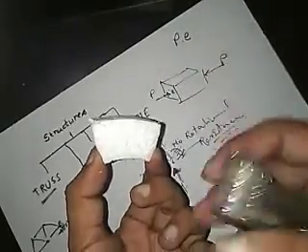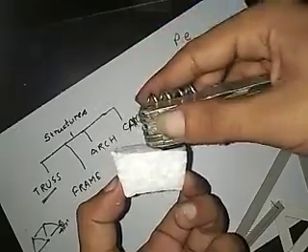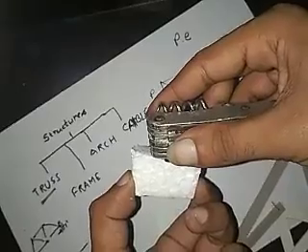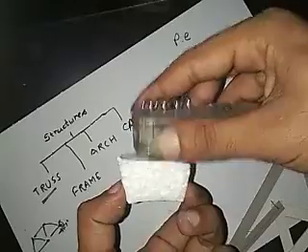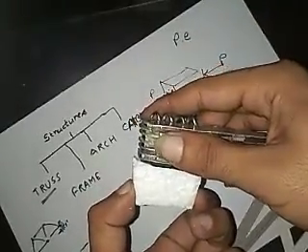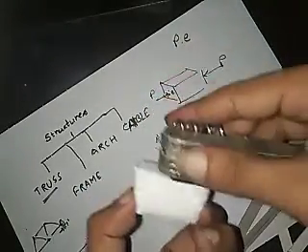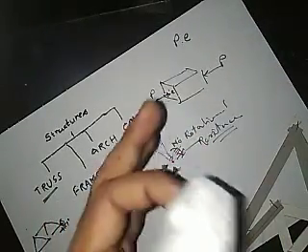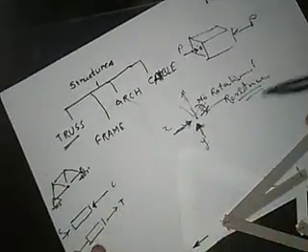So we apply some hogging moment, and that is counteracted by the load when it occurs on the structure. It releases some stresses, and there will be a lesser amount of sagging, or almost zero sagging, because we have already applied a hogging moment, and that is counteracted by the application of the load. So that is something which we are avoiding in the discussion of trusses, because we are assuming that